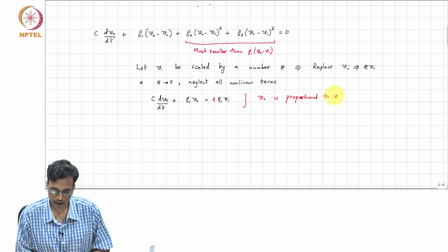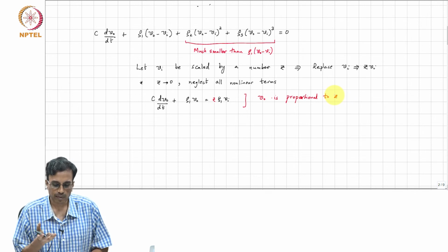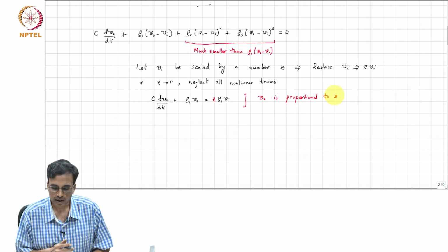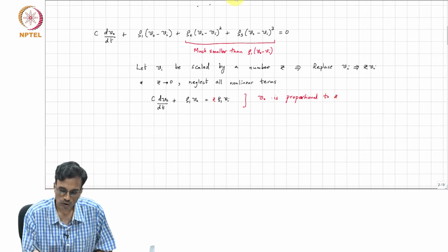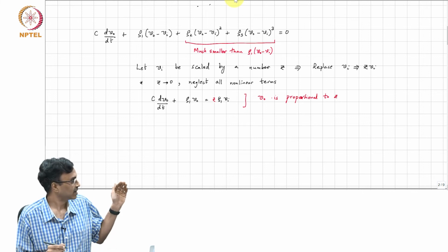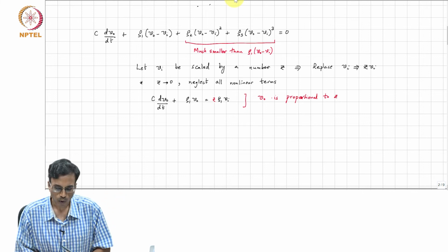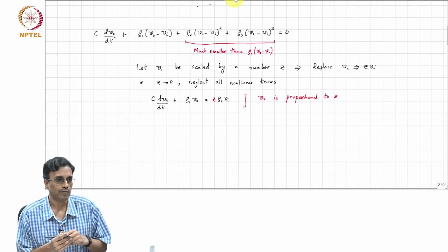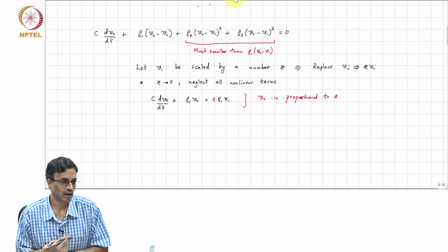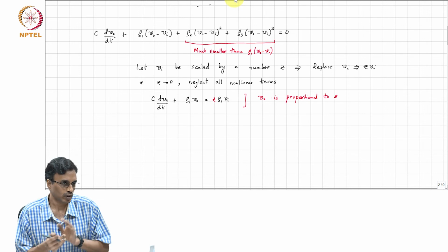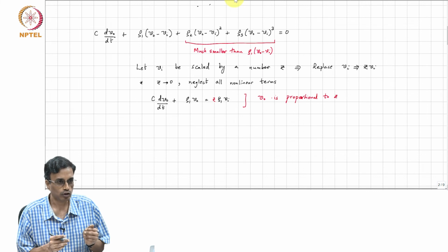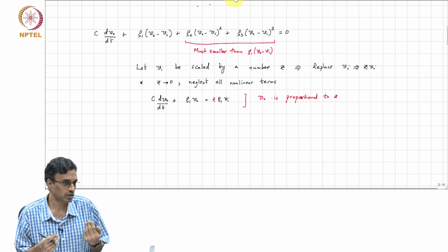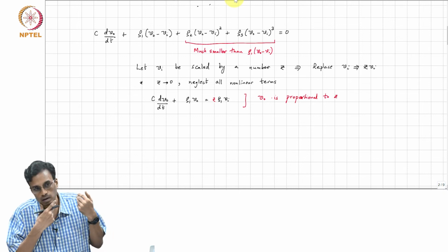Okay. All right. Now, let us say Z starts becoming larger and larger, so that the nonlinear terms can no longer be neglected. Based on our experience with second and third order nonlinearities, what comment can you make if you go on increasing the input amplitude due to second order nonlinearity? Apart from the linear term, you should also expect a component that is proportional to 2 times G2.